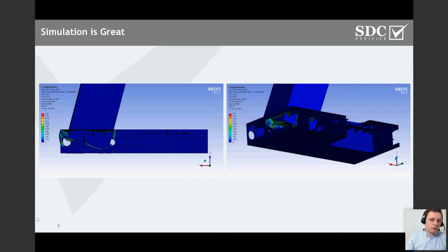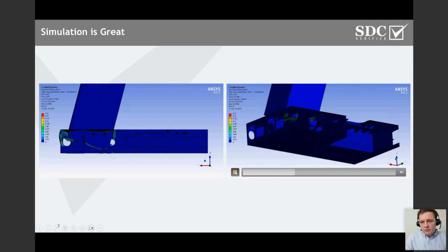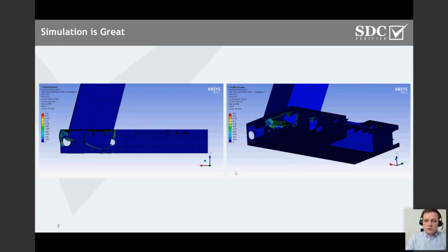So it was extremely important to make sure that in case of an accident, and these containers were occasionally lifted above the deck, in the most unfavorable condition, it's not going to break through the second deck, and it's not going to cause any harm or affect the cargo under the second deck. So you can do this kind of simulation with explicit dynamics.